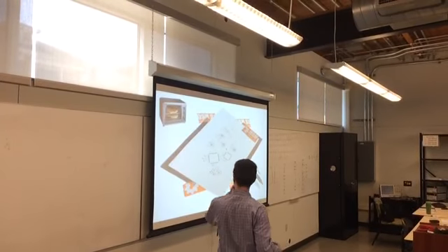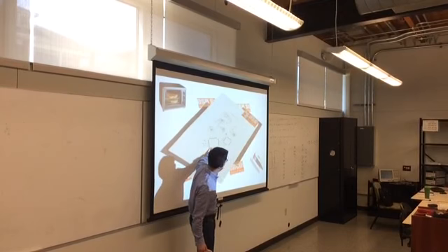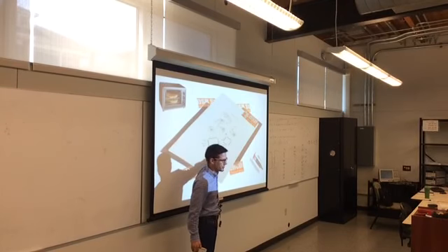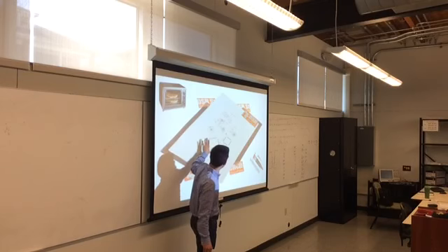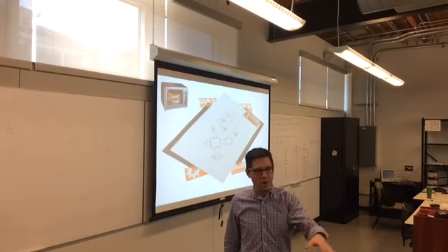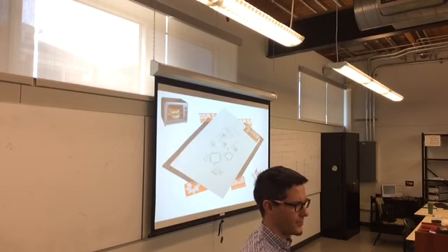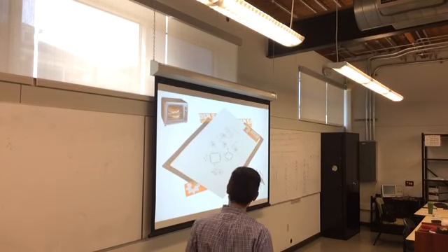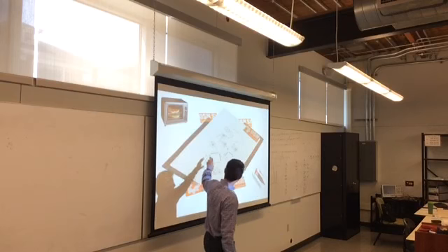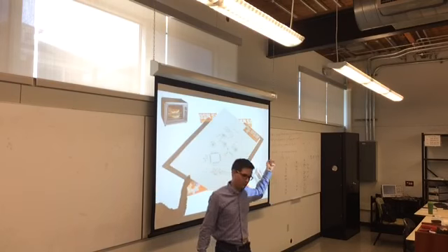It's not that hard of a process, but look at all these components. If you shift this board a millimeter to the left, you're going to smear everything and nothing's going to land. So you have to really tape this down and make sure that when you put the paste on, it ends up where it's supposed to. And if it doesn't, wipe it off, do it again, because you don't want to place the paste, have it smeared, and have all of your components short.